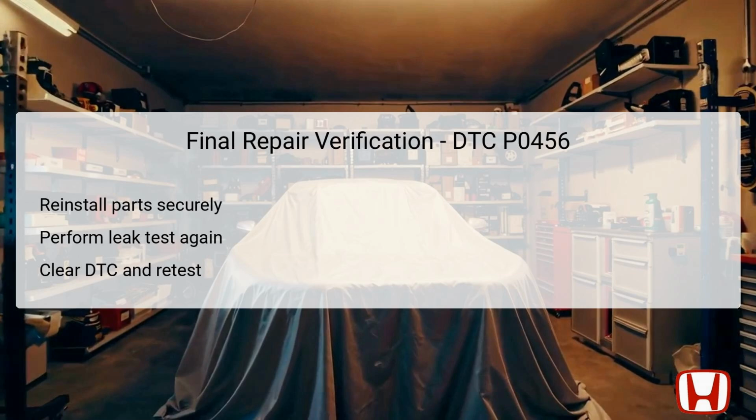Turn the ignition off, then restart the vehicle and perform the leak test again by running the EVAP function test through the HDS. Ensure the DTC does not return, confirming the leak was effectively sealed. Resetting the ECU is also part of the verification to clear stored codes and allow the system to relearn. This final step verifies that the repair has resolved the small leak and that the vehicle's EVAP system is now functioning correctly without triggering the DTC again.